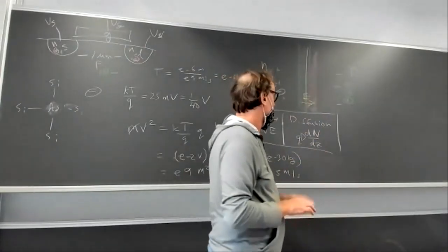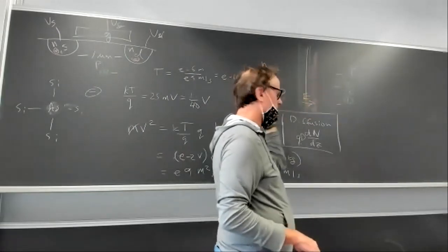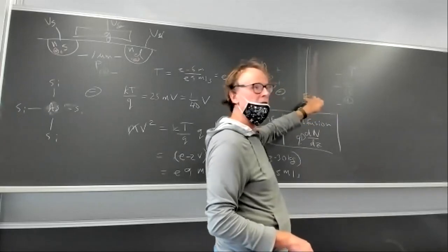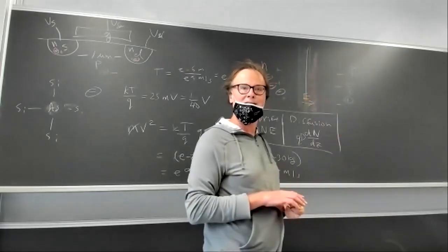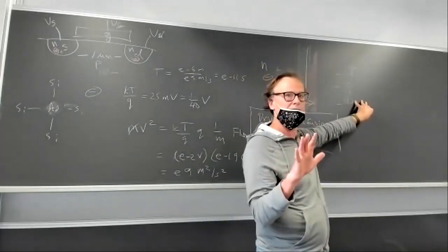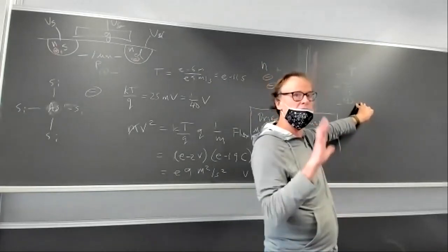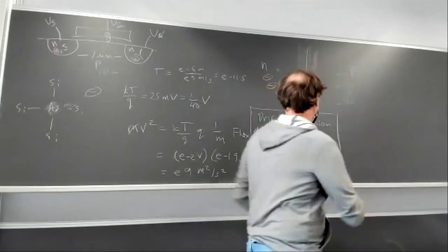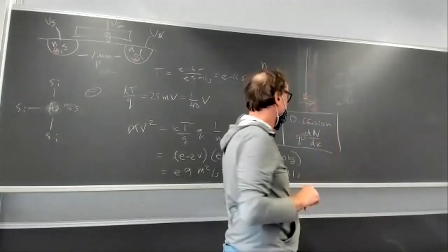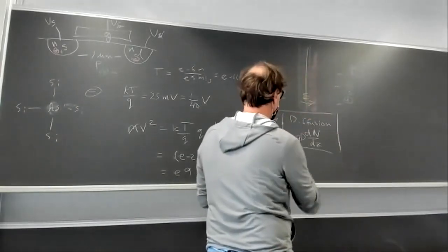Okay. So what happens is there's a big diffusion current for both electrons and for holes. But that's put in balance by the electric field acting on the concentration gradient everywhere. Out here, there's no concentration gradient, right? It's all neutrally charged. There's no net current everywhere, but there's no drift current, there's no diffusion current, right? Everything's just uniform. Right in this depletion region here, this so-called space charge region, you have just the bare carrier is exposed. And let's see how this works out.